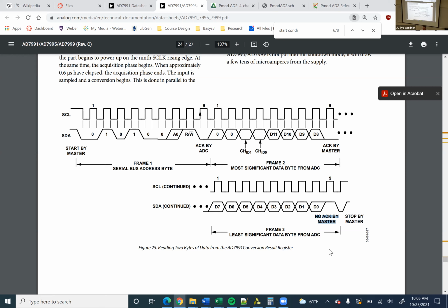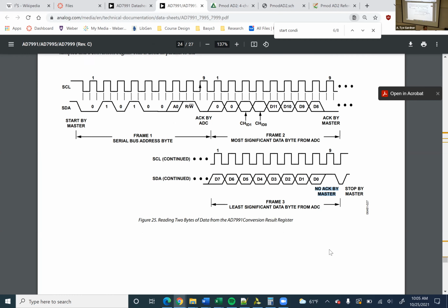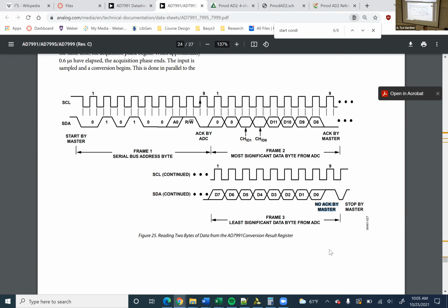Here it is. Okay, so this is why being able to read data sheets is important. I'm introducing you to an easy level, which is just this data interface, because all devices are always just a little bit different. And assuming that you know what it is without reading it is going to get you into trouble. So again, read is send the address, tell it to read, it will acknowledge, you'll take the bit, you'll acknowledge, it'll send you the remaining bit, you'll stop. Okay.